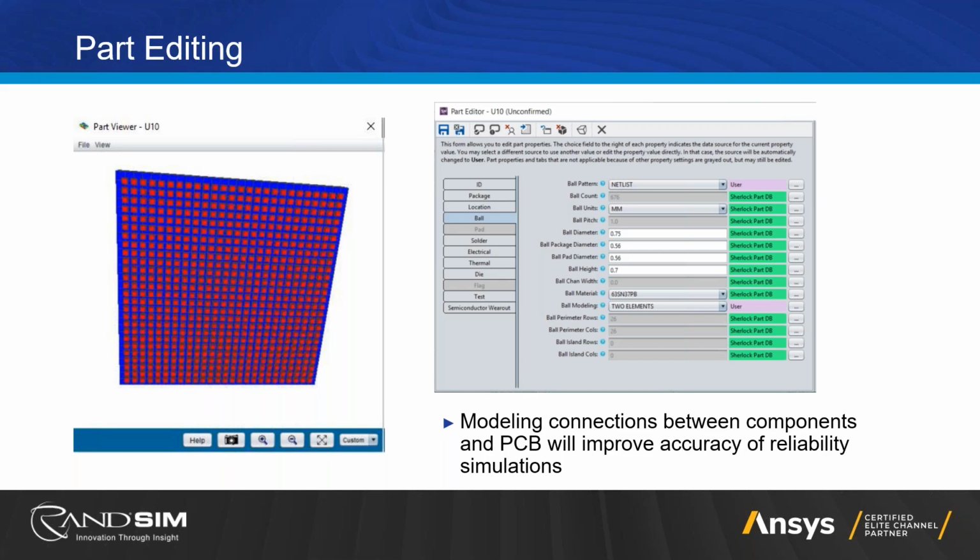And I want to go back to the discussion about component shortages. I think we're all feeling that pain in some way or another. And when you're swapping things out, specifically silicon stuff like ICs with BGAs, from manufacturer to manufacturer, there may be a little bit of a variance in what those solder reflow patterns or the solder paste layouts look like.